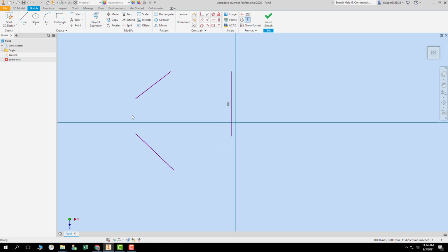I wanted to show you they don't have to touch. Okay, 3 lines. Now, if I go over and say circle tangent to 3 lines, instead of finding the center point, which we don't know where that is between these 3 lines, we will touch this line and click, touch this line and click, and touch the 3rd line and click, and look what it does.